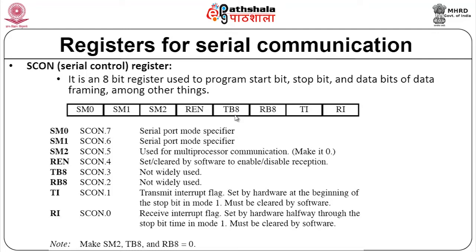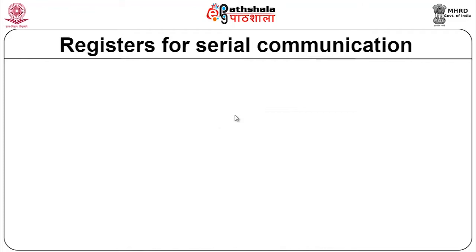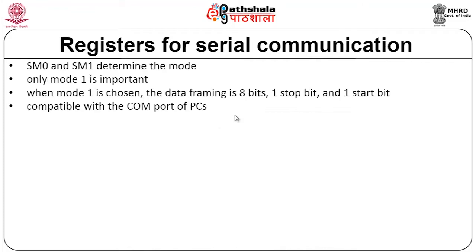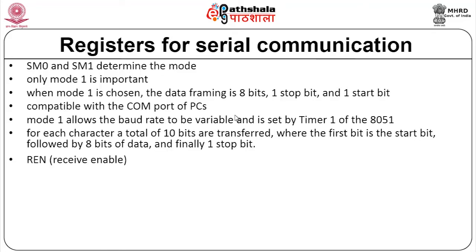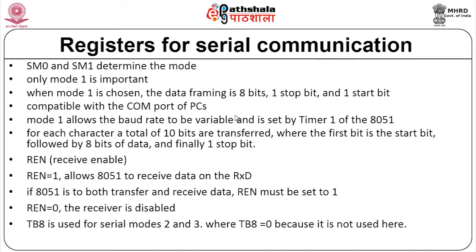When you are sending data, it will be sent with a start and stop bit. We should remove the start and stop bit before processing the data. That is also something we have to consider. Now when you look at serial communication, I have SM0, SM1. Mode 1 is always preferred, where there is one start bit, 8-bit data and one stop bit, so totally 10 bits.